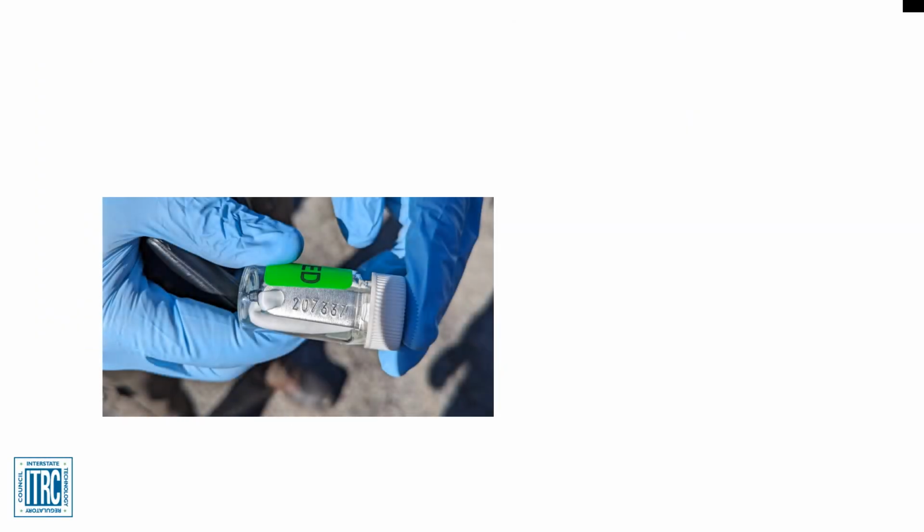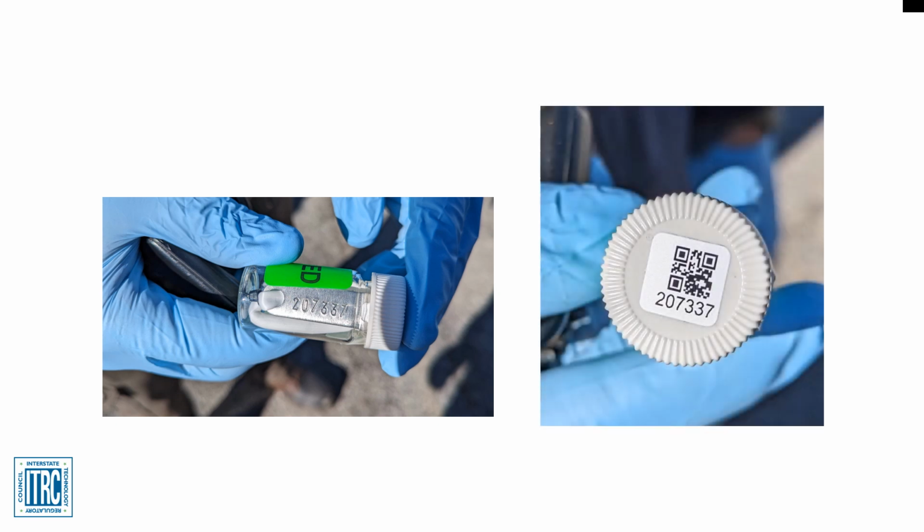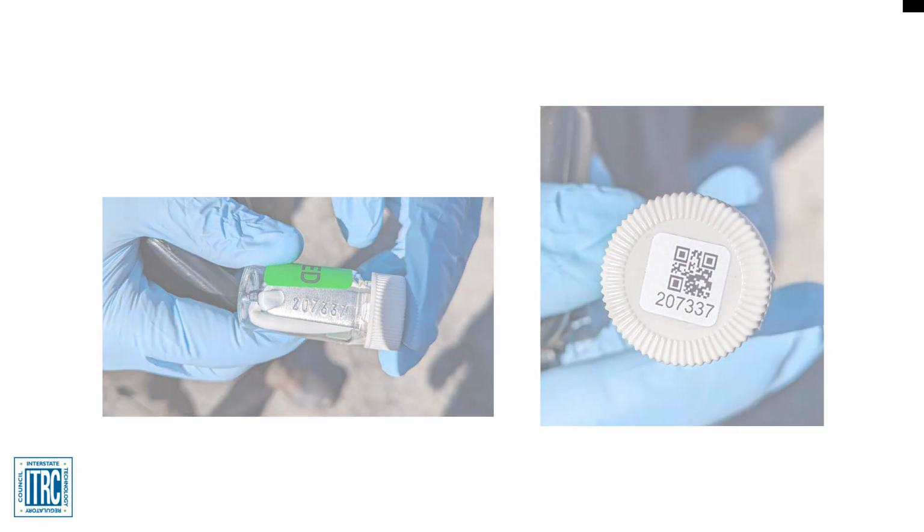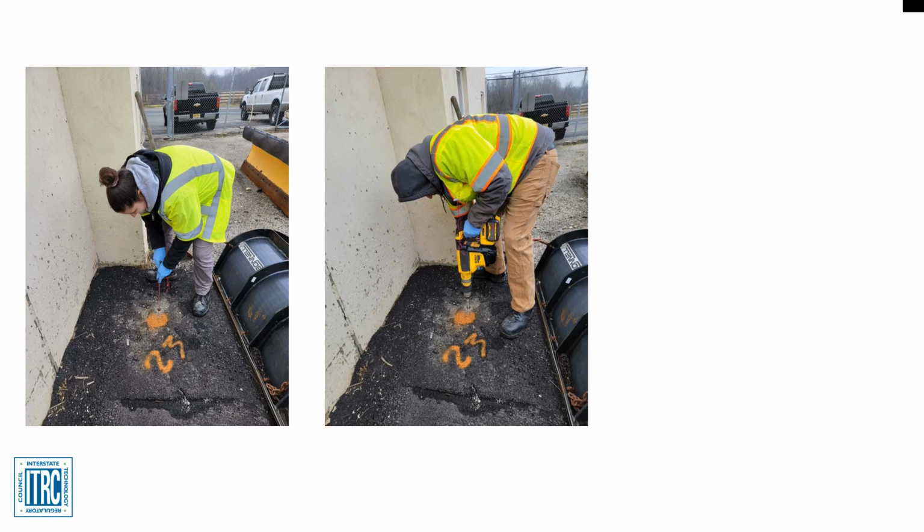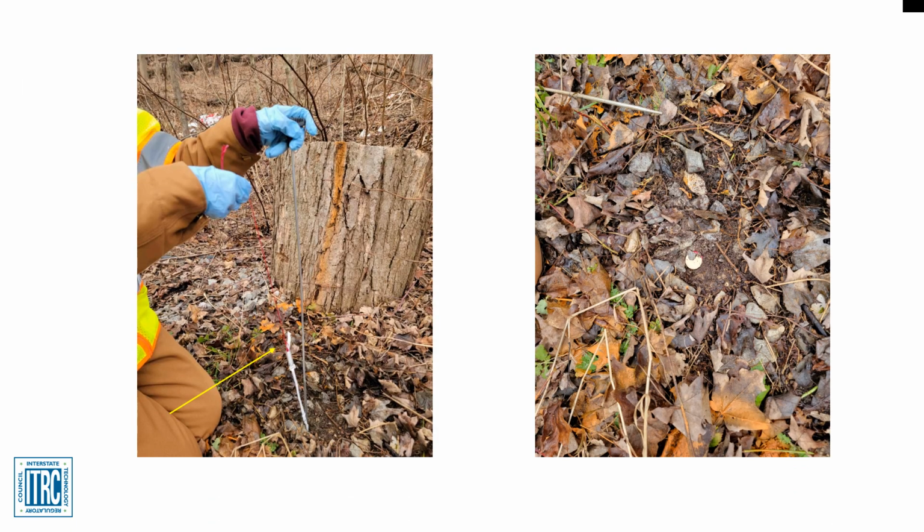When deploying the AGI sampler to collect soil gas samples, follow these steps to install the device. Before going out into the field, verify the sampling kit provided has all of the necessary supplies and that the serial numbers on the samplers match those on the glass vials. In the field, drill a vertical boring at least 1.2 inches in diameter and up to 36 inches deep. Once the boring is drilled, the field personnel must cut a 72-inch length of string and loop it through the eyelet of the supplied cork.